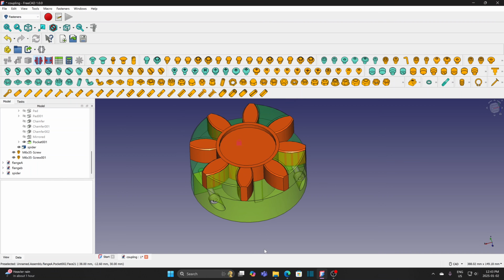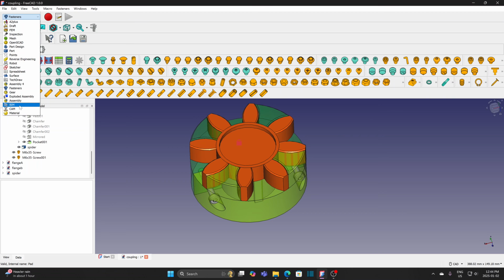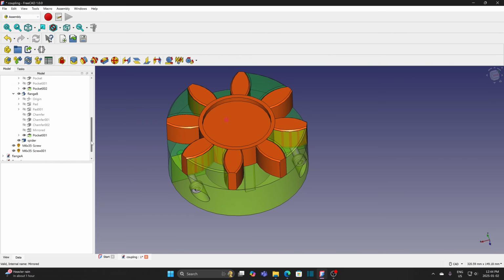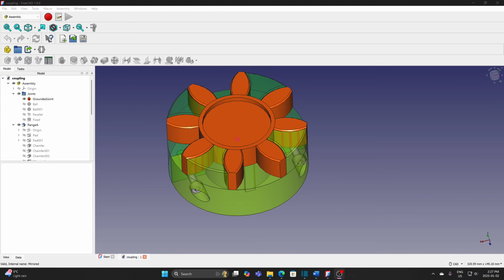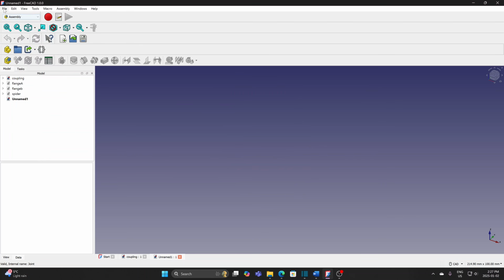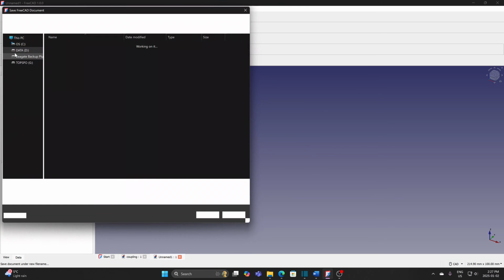Besides, the ball joint can be created between a plane and a line, a plane and a plane, or with round surface. The joint is created between the center of these bodies. Let me do a quick demonstration about this. Create a new file and insert files line and round plate.